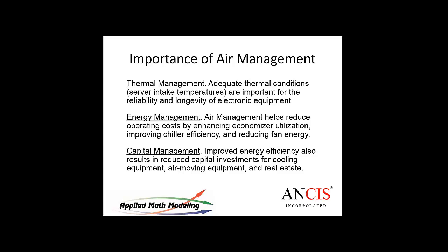Or recovery of capacity, for example, in a raised floor. Many raised floors are a little bit overwhelmed by flow rates today, and the main reason is probably that there is very poor air management in the space. So if you rearrange the space with good air management, you will notice that the capacity of the floor is coming back to you. And maybe you don't need to build a new data center because you have more capacity than you think in that raised floor. That's right.